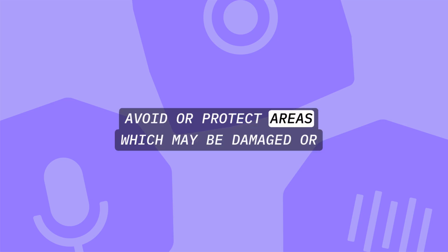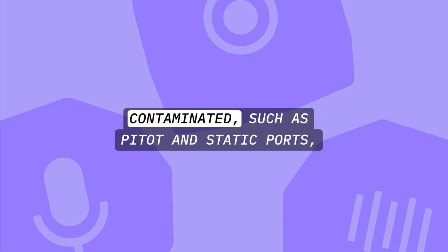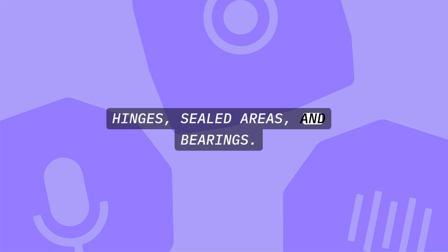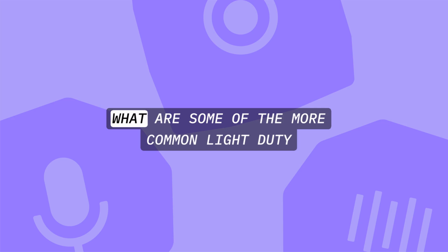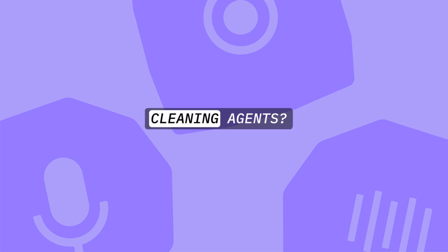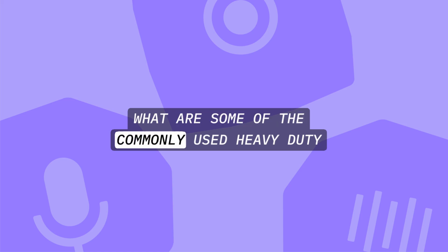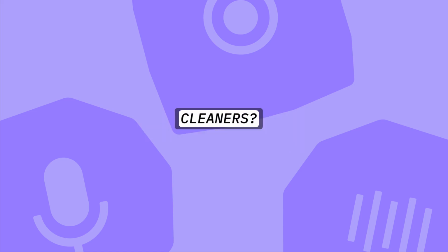Avoid and protect areas which may be damaged or contaminated, such as pitot and static ports, hinges, sealed areas, and bearings. What are some of the more common light-duty cleaning agents? Soap or detergents and water. What are some of the commonly used heavy-duty cleaners?